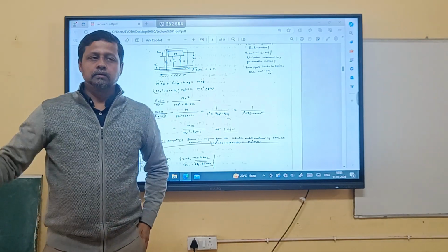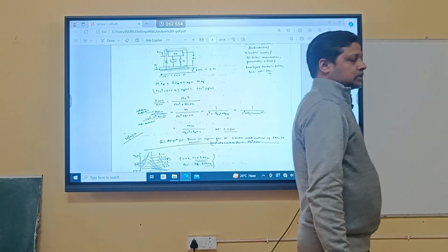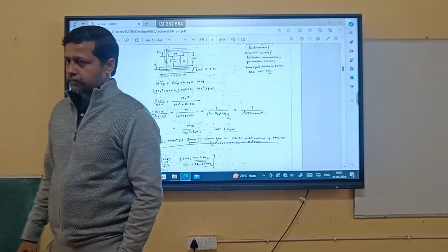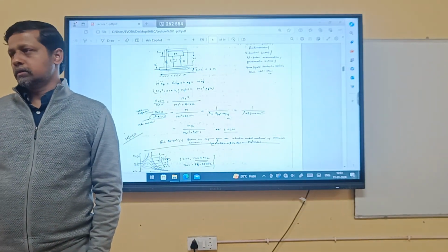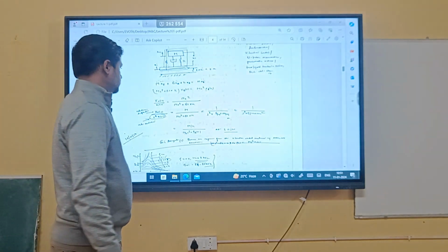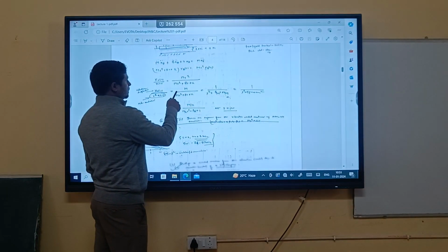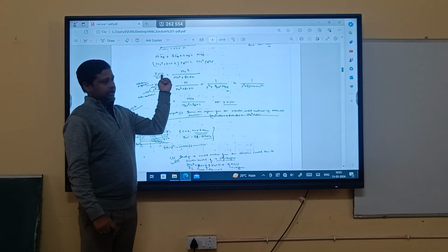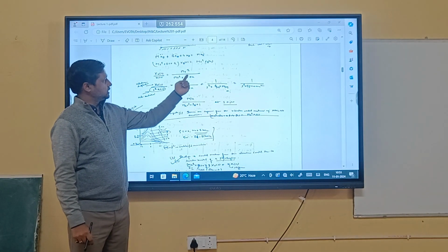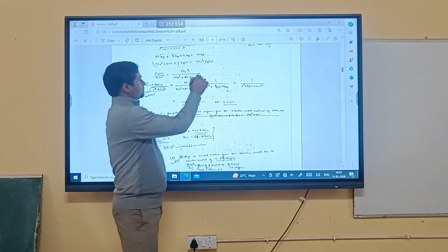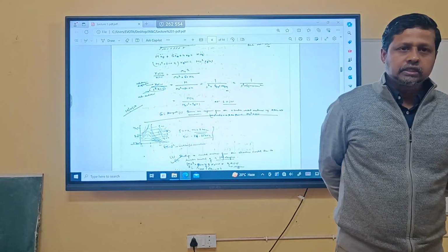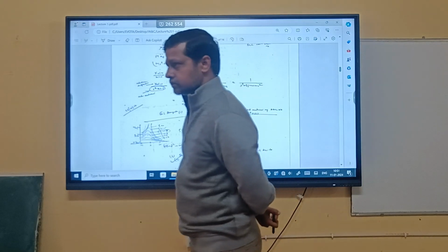Now can you solve this and find out your transfer function in the S domain, of course. Don't solve it now in the time domain. Solve it on the frequency plane so that you can easily get it. Now you see here the response you are getting: X naught(s) upon xi(s) is equal to m s square upon m s square plus b s plus k. So you can name these, equation number 1, equation number 2, for your better understanding. Is it clear? Are we clear about it? Right?